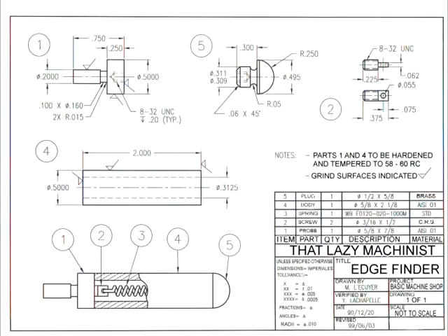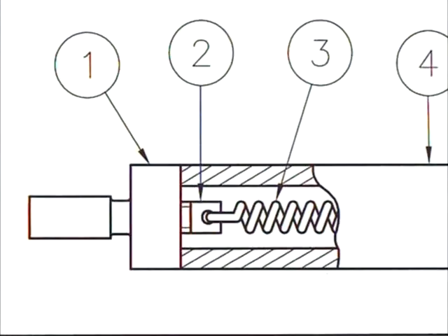And although they are made to simplify the reading of a drawing, oftentimes they confuse people because they're not quite sure what they're looking at. So let's take a look at some examples of sections. Here is a really informal type of section. I wouldn't even call it a view. It's more just a window to the inside of a part. I call them broken edge sections, and they are generally found on assembly drawings.